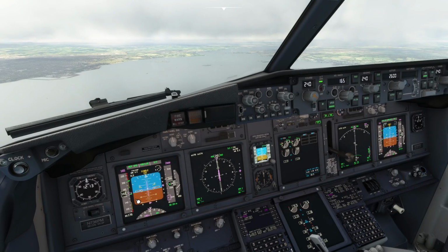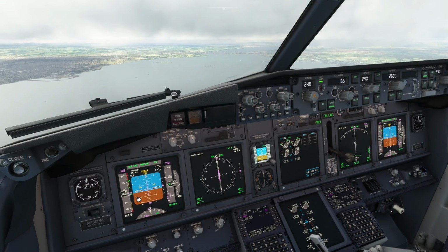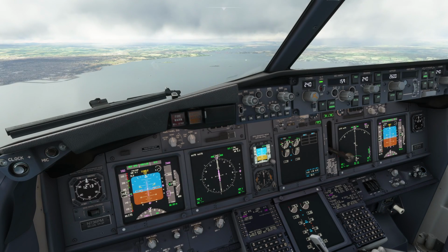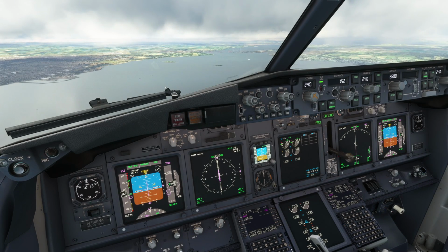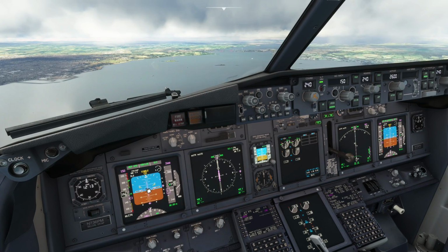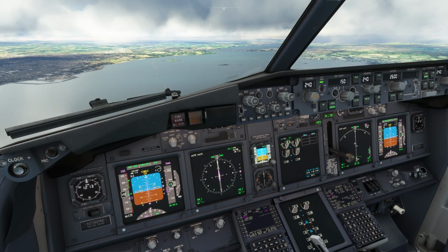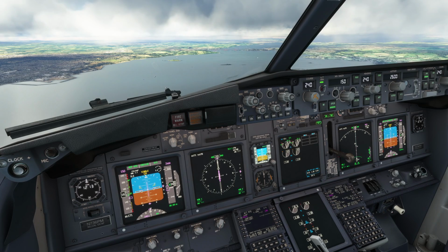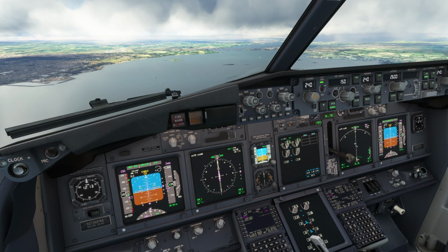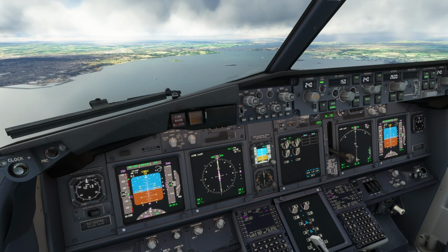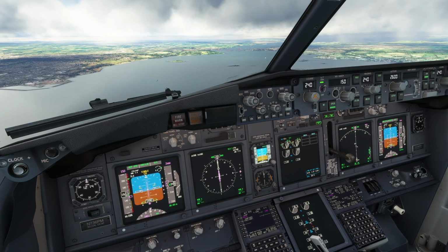The airplane will be managing its speed now. We notice we've gone into speed mode, so it's up to us to get rid of the speed for finals. If we say we want 150 knots, the speed will come off. We can go to the next level of flaps. Here they come. 2,500.